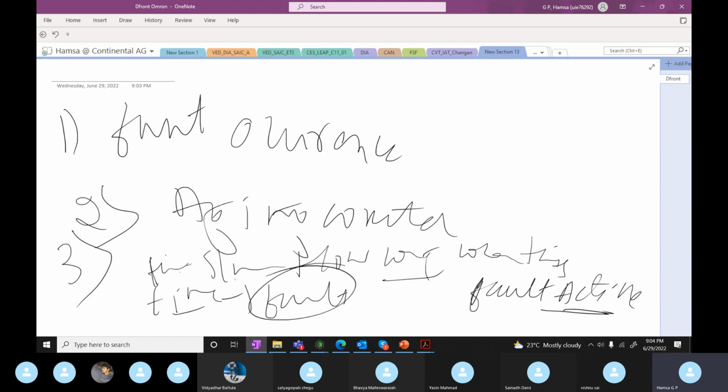So twice or thrice it will be checking, and there is also a time: how often the system will check for the faults. It's every 10 millisecond, it could be every 100 millisecond based on your task. You guys will create the tasks: 1 millisecond task, 2 millisecond task, 3 millisecond task, 1 second task, 2 second task, 3 second task. Based on that, it will be checking for all these faults.